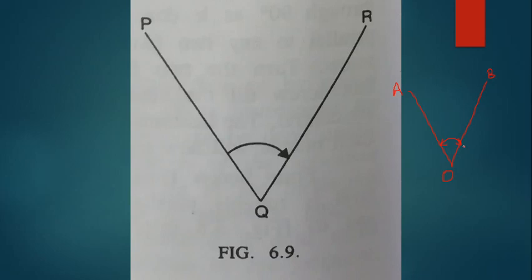The angle is measured clockwise with face left observation once, and then a number of repetitions, minimum 3; we can take 4 or more also. If we require more accuracy, then we go for more repetitions. But generally, in practice also, we go for 3 repetitions.